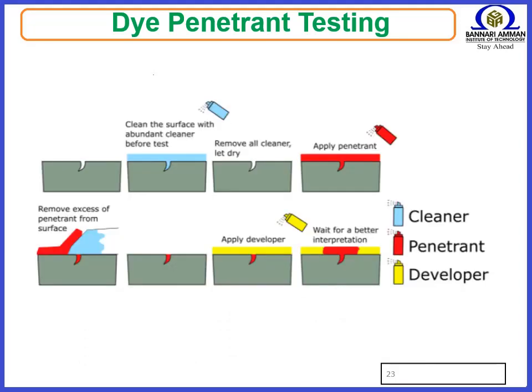Advantages: high sensitivity to small surface discontinuities. Easy inspection of parts with complex shapes. Quick and inexpensive inspection of large areas and large volumes of parts and materials. Few material limitations: metallic and non-metallic, magnetic and non-magnetic, and conductive and non-conductive materials can all be inspected. A visual representation of the flaw is indicated directly on the part surface. Aerosol spray cans make the process portable, convenient, and inexpensive.